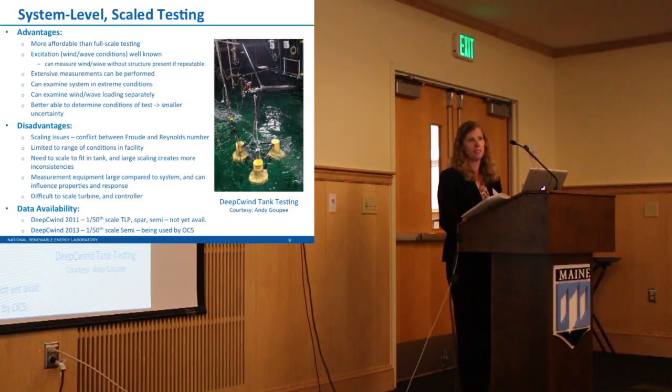You can also examine the system in extreme conditions because you can apply the wind and waves such that an extreme condition happens. If you're out in the open ocean, you have to just wait for it to happen. And you can also do a stepped approach, which is very beneficial to look at how the system responds for specific types of excitation. So you can look at the wind and waves separately. And you also probably have less uncertainty in the tank because you're doing a lot of the prescription yourself and you can better understand it.